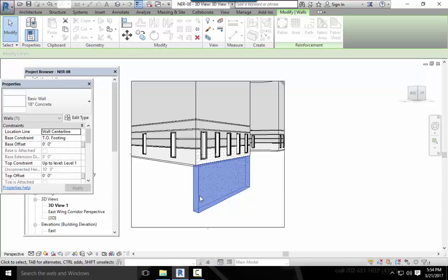What happens when water freezes? It expands, right? So what happens when ground that has a bunch of water in it freezes? It displaces. It expands. And if your footing is above that, what happens to your building? It will rise in some places and not other places. Buildings don't like that. It's called differential movement, and it causes cracks and structural problems.